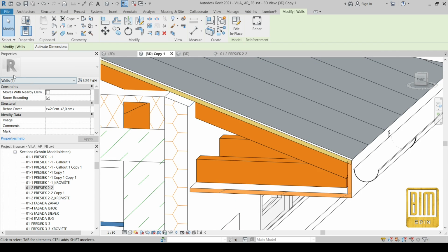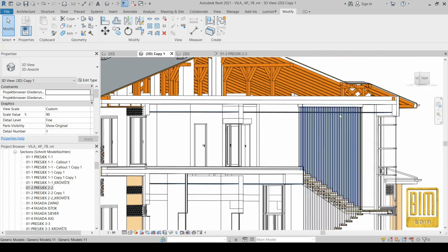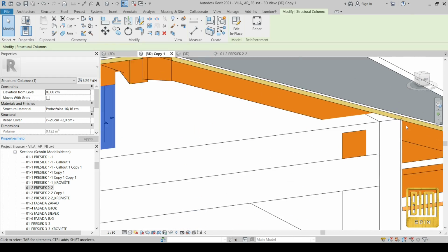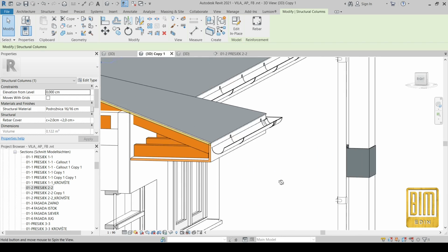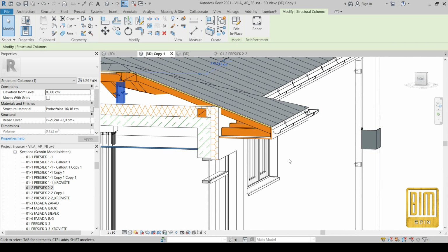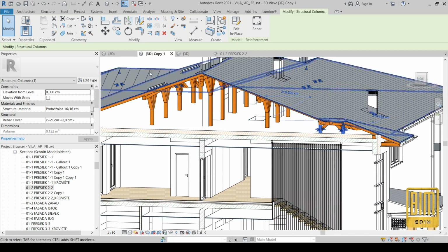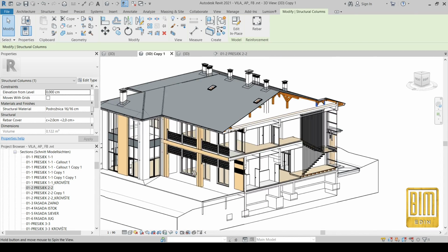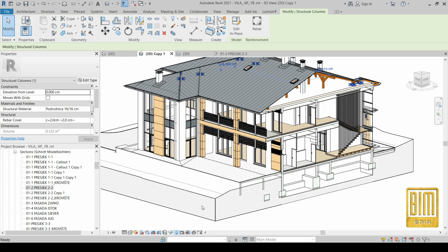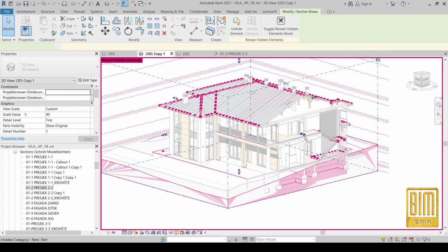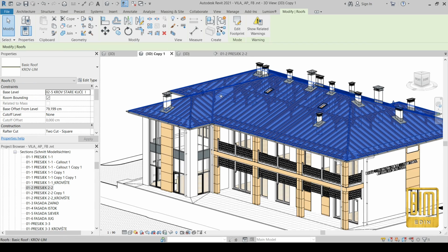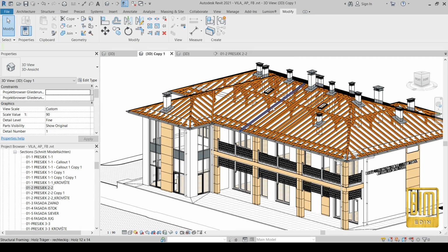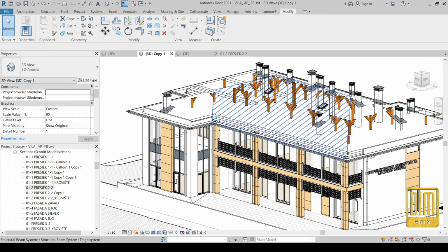All right. I use the void to cut this part of the walls. As I said before, you can cut wall in any form you need, and you can create this kind of solutions using model in place and using wall void form.